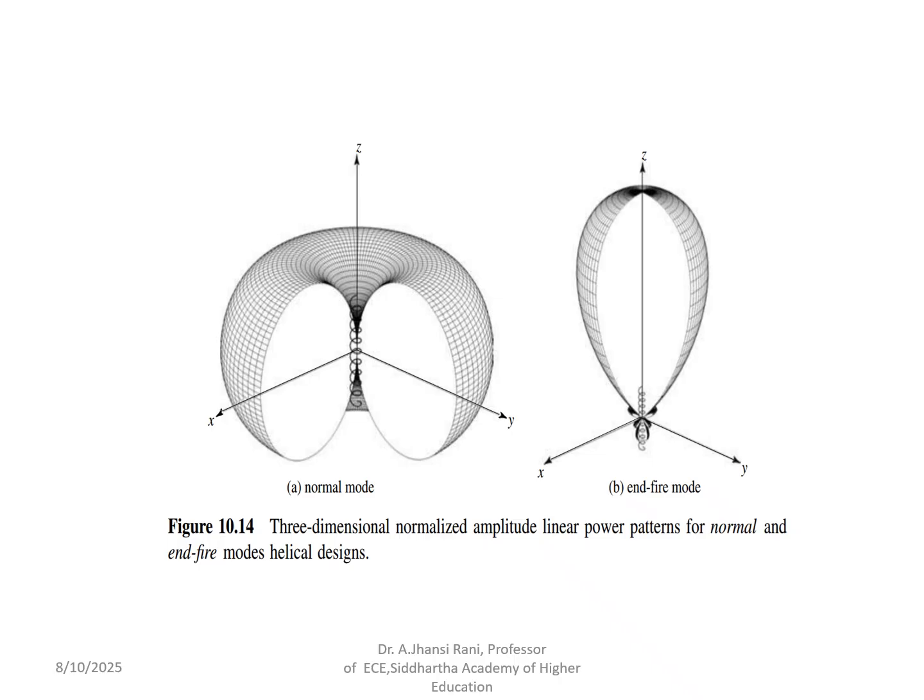In the end-fire mode, the radiation pattern is maximum in the direction of the helix axis, the axial direction. In this mode, the helix must satisfy 3/4 < C/lambda < 4/3, that is, C/lambda approximately equal to 1, and the pitch angle is between 12 and 14 degrees. Other types of feed, such as waveguide and dielectric rods, are also possible in this axial mode of operation.